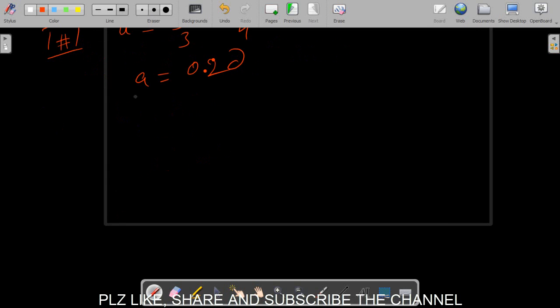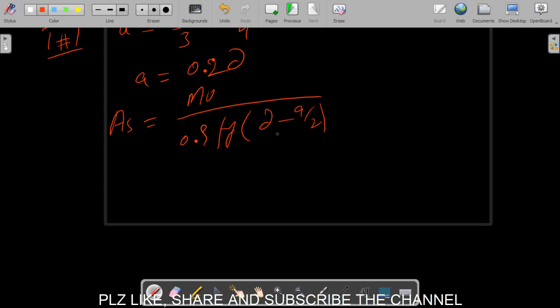After finding the value of a, we will calculate the area of steel, that is, area of steel equals Mu divided by 0.9 Fy into (d minus a over 2). And then we will use the second trial.